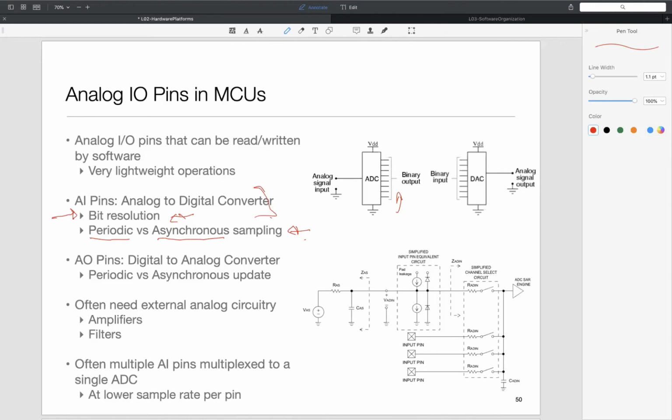So remember, the more the bits, the finer the signal you can hear, right? I mean, 1 bit corresponds to the sensitivity. So if you have played with Arduinos and all, what do you think is the typical bit resolution that you encounter? Rough ballpark. Is it like 4, 5? Is it like 8, 10? Is it like 20, 30? What ballpark? Like 8 to 12, maybe. Yeah, 8 to 12. 12 to 14 would be a good one.